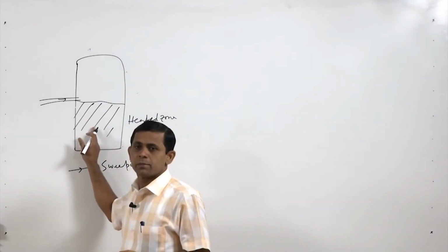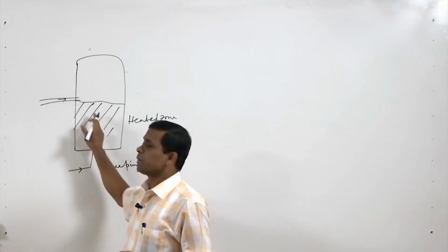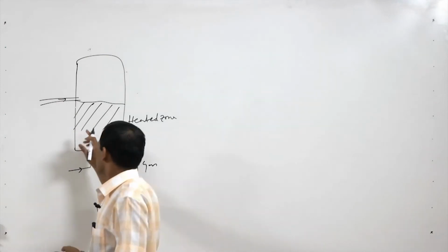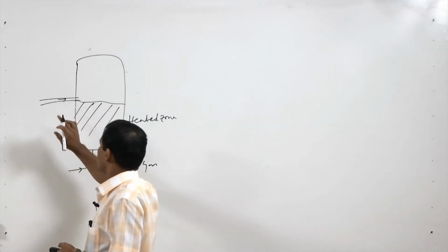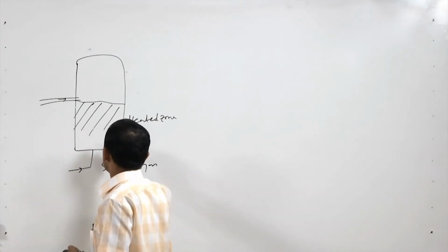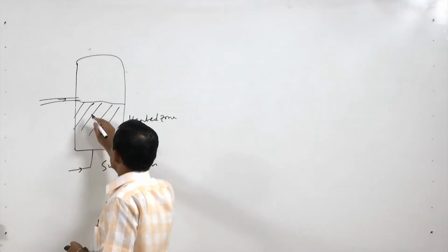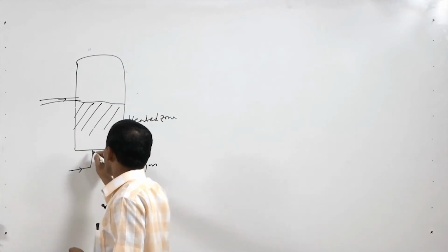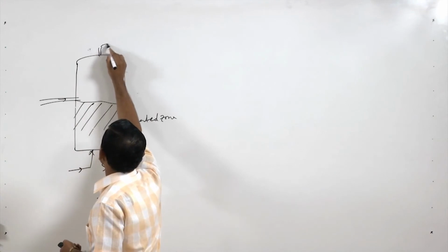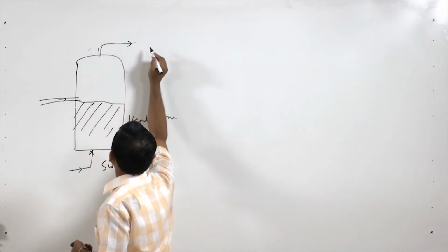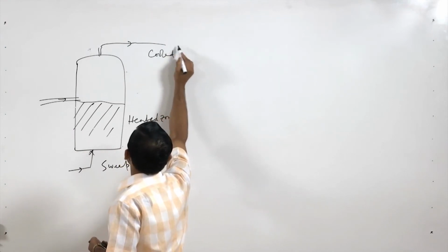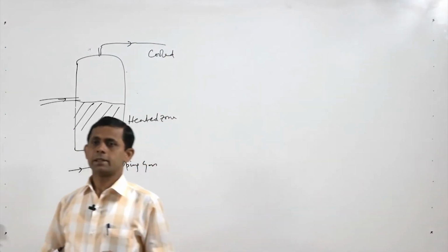As the temperature is maintained here, biomass and waste come here, so pyrolysis will take place, but here the diameter of the particles may be bigger, with no limitation on the diameter of the particles. When it comes in this hot gas, vapors will be created through pyrolysis and they go off, and further they will be cooled and we will get bio oil and the gases.